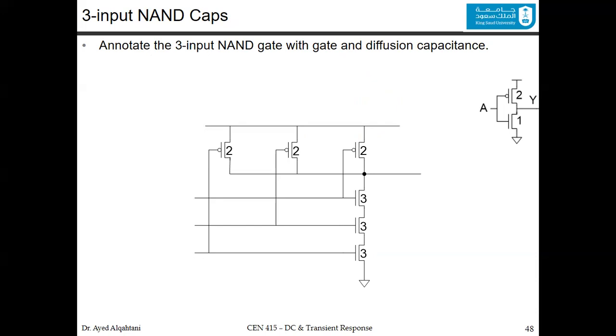We said that the node of the VDD here, since it's always connected to the VDD, and this node here is connected to the ground, we don't have to consider their capacitance. They won't take any time from you, so don't worry about these connections for the capacitance. The sizing we already put them. The first important node that you care about is the output.